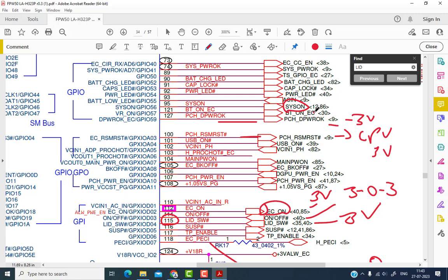This information is going to page number 86 and 12, and this signal will turn on the RAM supply. The RAM is DDR4, so 1.2 will be generated after generating this signal. Then the next signal is called main on.